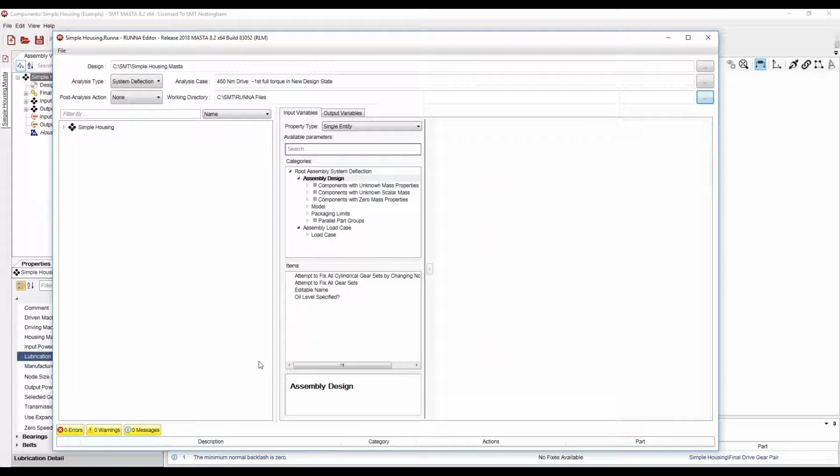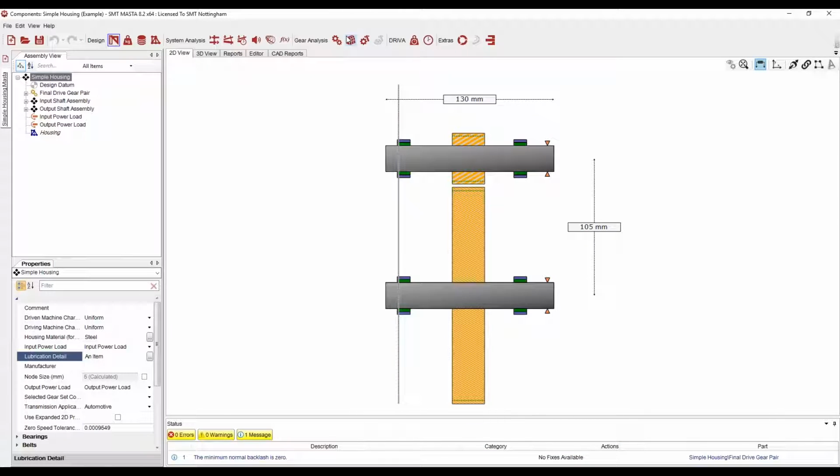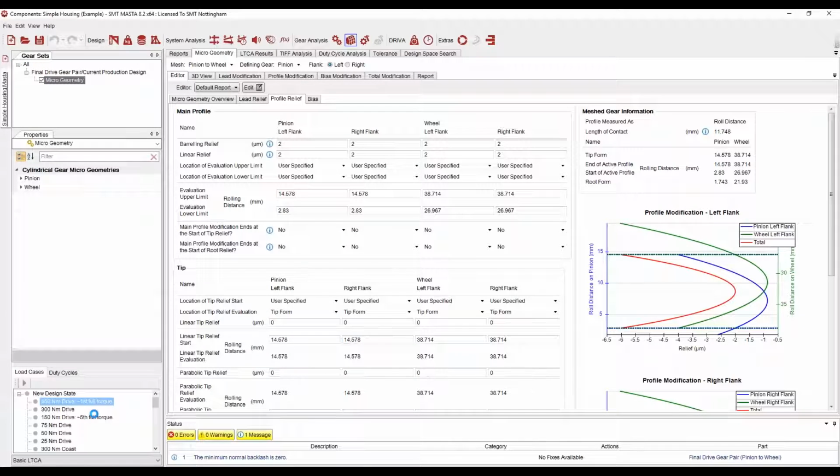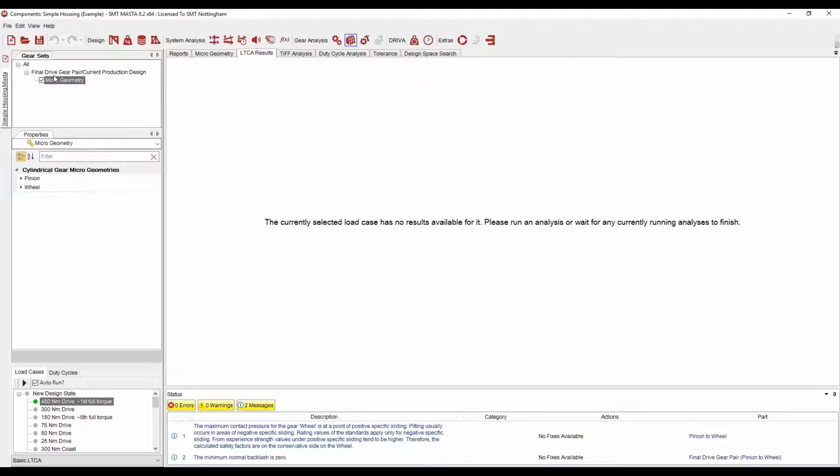So in this example, I'm going to look at the effects of crowning, barreling, and torque on the transmission error, the contact chart, and also the housing response. So if I change the analysis type here to gear line analysis, so I can get the housing response results, I'm going to go back to my model and see which flank is loaded again. So microgeometry mode. Let's run the load case. So in this example, it's the right flank.